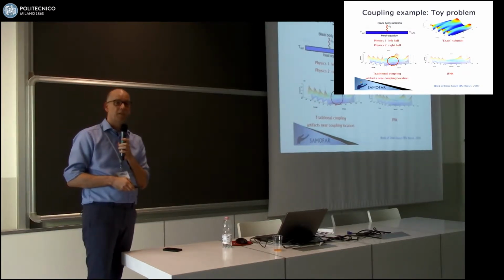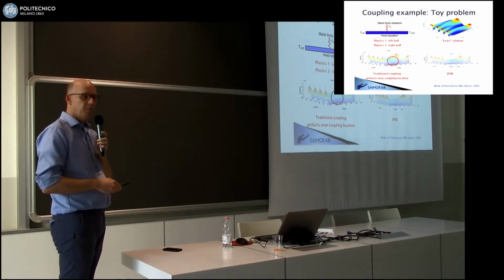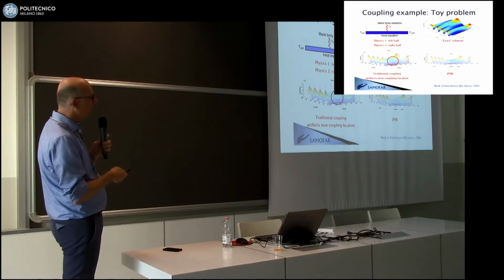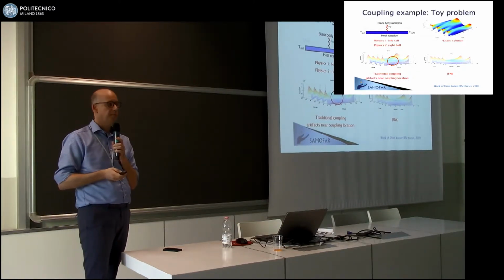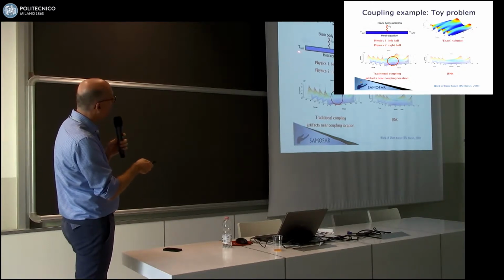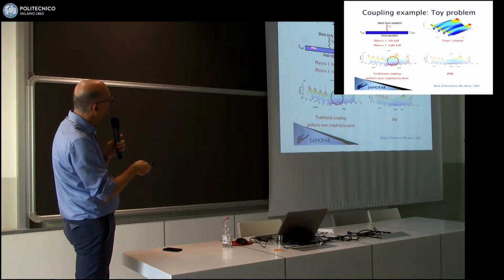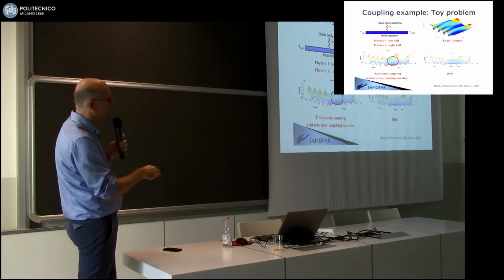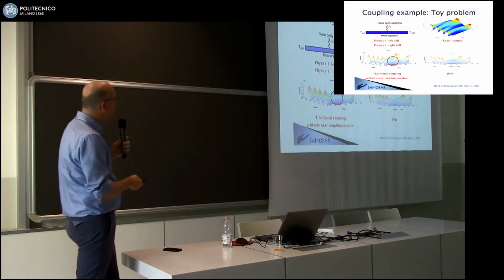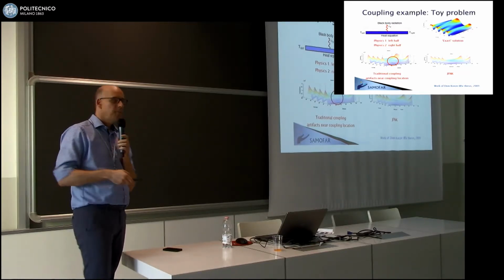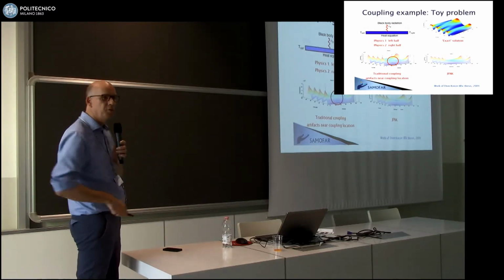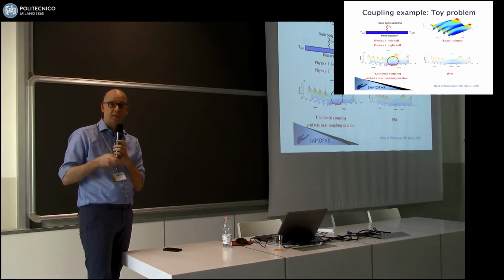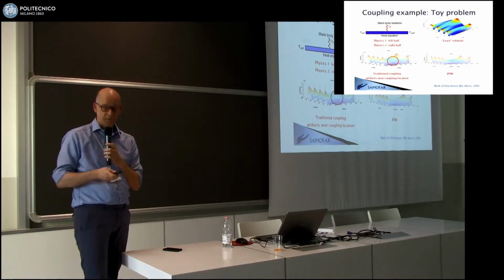Now the student, of course, worked really hard, and did a couple of examples. And it does show you what the problem is with this traditional loose coupling. This is a, you could say, single physics problem, that of a conducting rod. There's a temperature given here and a temperature given there, and they're oscillating. So that's what you see here. And this is the exact solution to the problem. So these boundary temperatures are oscillating and heat is conducting all over the place. And what do I then do to make this a multiphysics problem? I simply cut this thing in the middle. Then I've got two physics problems that are connected together through the boundary condition. So it's sort of an artificial multiphysics problem.